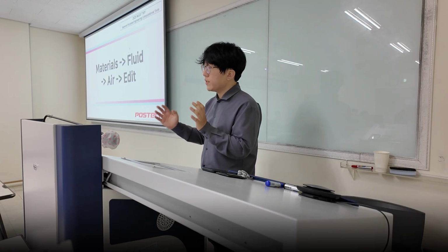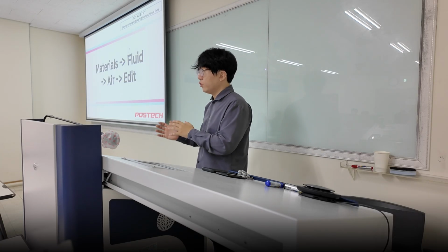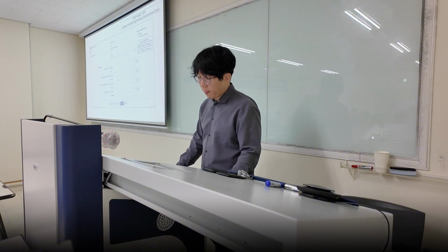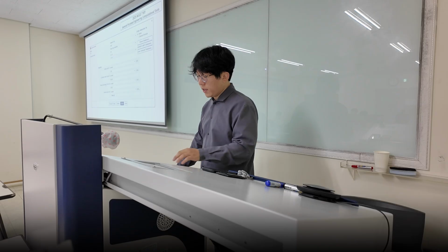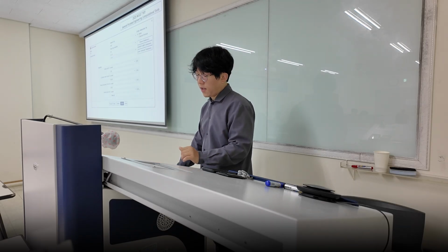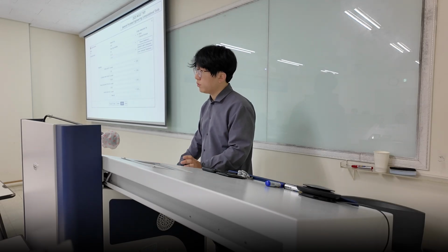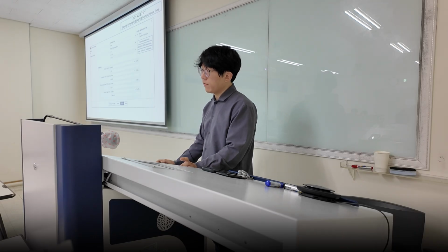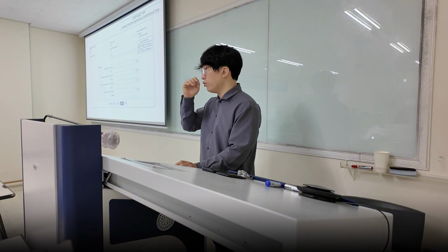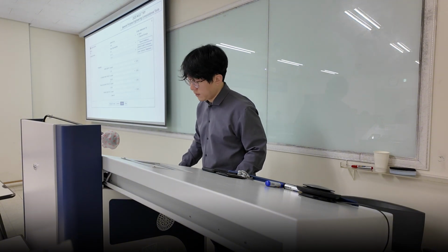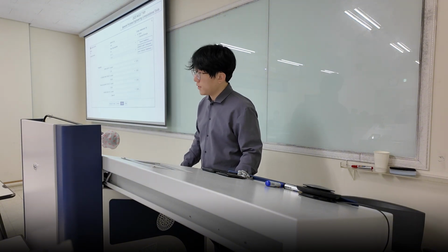Once we set up the model, we're going to define the fluid and solid properties. We're going to use air, and we're going to have the properties constant. In some cases, you can have variable properties, and sometimes you have to couple a user-defined function, called UDFs, to use these as variables.